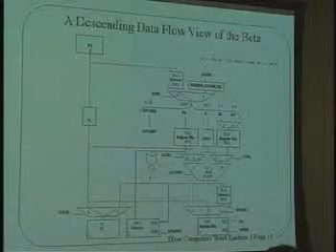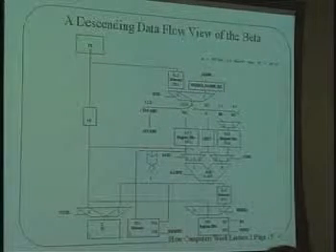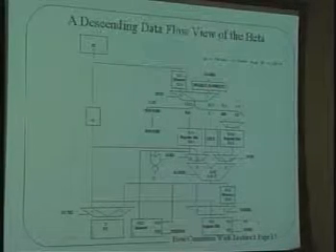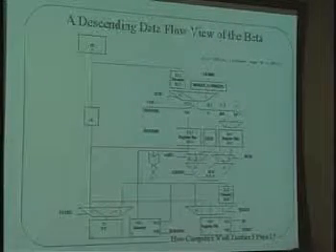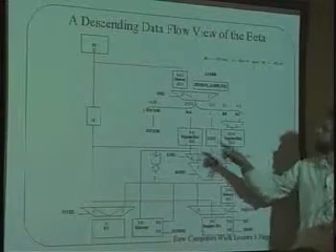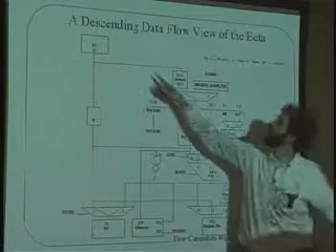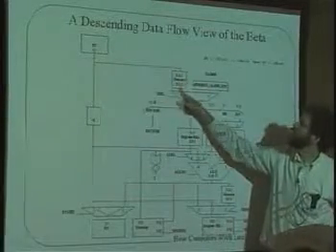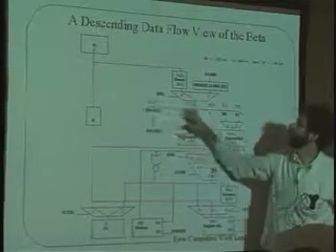So now we've handled storing the PC plus 1 into register C. Now we've got to test the contents of register A and see whether it's 0 or not. And the way that we do this, and unfortunately I kind of didn't quite do it all the way here. The instruction comes in here just like it always did, and comes out here and is decoded into different fields.